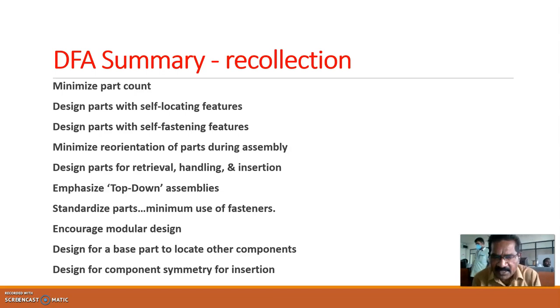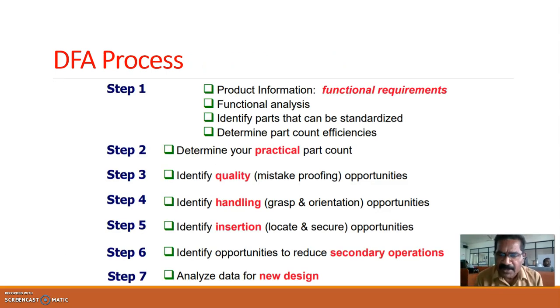Encourage modular design, so that the individual parts can be removed and then put back again for easy replacement, etc. Then design a base part to locate other components. Design components for symmetry for insertion. The steps are like this.